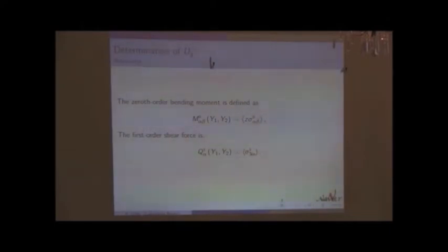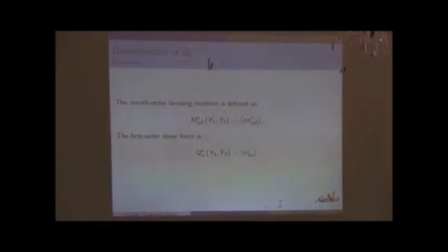So I introduced the resultants, and actually I did it yesterday starting from an ab initio plate theory, just introducing resultants and equilibrium equation. I found a way to build a plate model. So I do exactly the same, but I select the correct orders for the bending moment at this order. So I'm integrating through the thickness sigma naught.